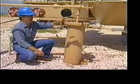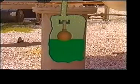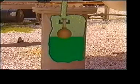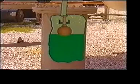Another safety device located here is a fuel gas scrubber. The fuel gas scrubber prevents entrained liquids from going to the burners with the fuel gas. If the scrubber fills with liquid, a float rises and shuts off a valve which stops the gas from flowing to the burners. This prevents the possibility of a fire.